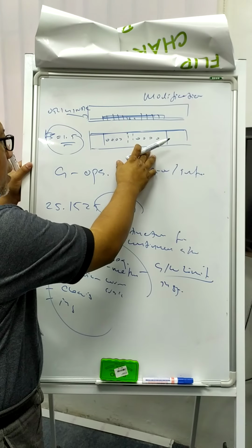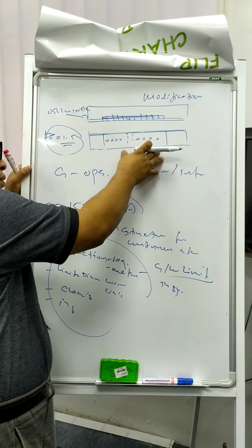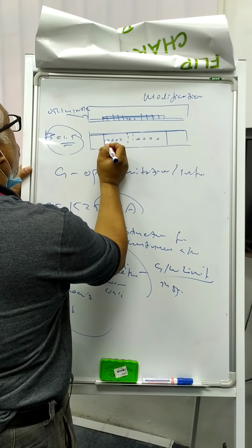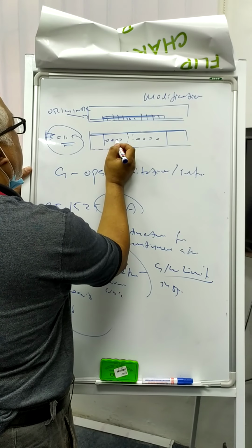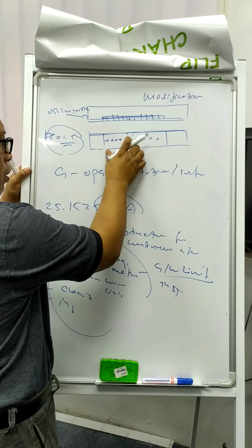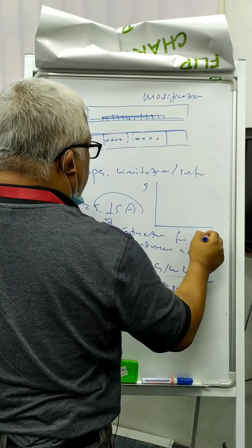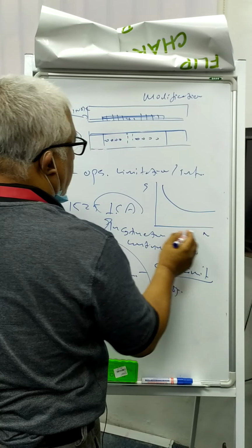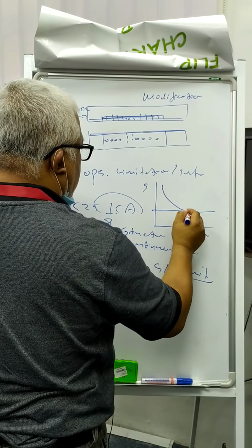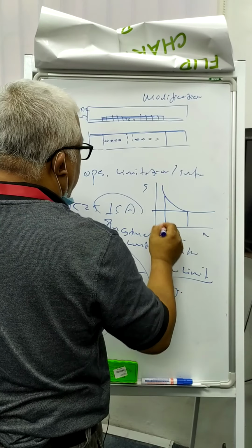You know why you need to inspect? Because when you do the repair, you only do the static. You may do damage tolerance and fatigue analysis. However, remember, as you cut more holes, you are putting in stress. Any cut, any corner, any hole, you put in more stress. So as you put in the stress, remember, if you go back to the S-N curve, stress versus cycles, if this is the stress now, because nothing is plain, but now you put more holes, you have increased the stress.